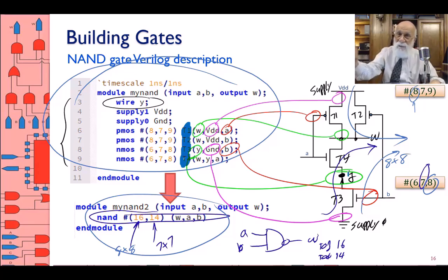And then what I do, I replace that entire transistor structure with a very simple statement saying, okay, I have analyzed my transistor structure, I have found a worst case delay for the 1 and for 0. From this point on, I don't need to do that slow simulation. I will put one little line describing my complex structure.